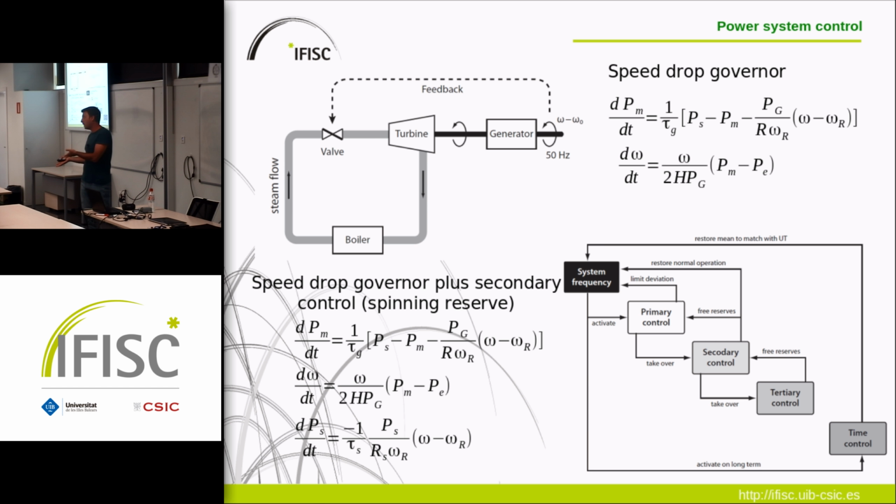But it's a very bad clock because 50 hertz is a very low frequency, so it deviates. What the operator does is every now and then synchronize the power grid with an atomic clock, so that's a reliable time. It's not relevant for this talk. We are only concerned with primary and secondary control, just to keep the frequency in a good range. Follow?